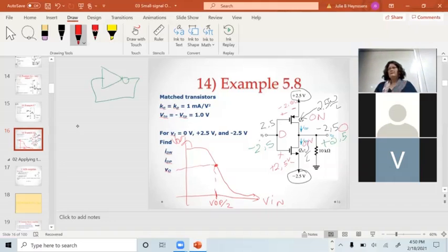It is an inverter that's actually operating with both transistors in saturation, and it ends up being in that linear range. And this is why this circuit here works. If the output is VDD over 2, that's the only stable point for it to operate at, because VIN has to equal V out, which would give you VM. Okay.